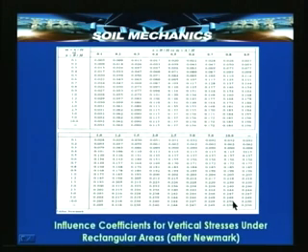That means practically all values of m and n, that is, from a rectangular area of very small dimensions to very large loaded areas occupying huge extents. We can determine the stresses beneath such areas for, remember, a uniformly distributed load. This particular table has been evolved by Newmark based on Boussinesq's theory.